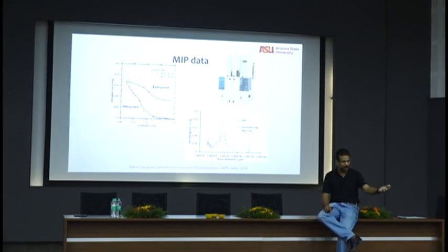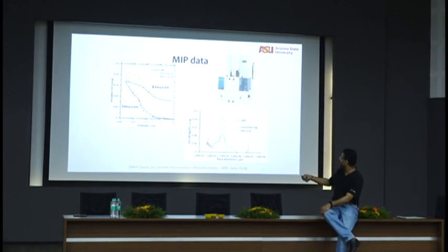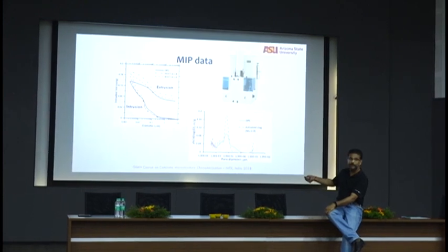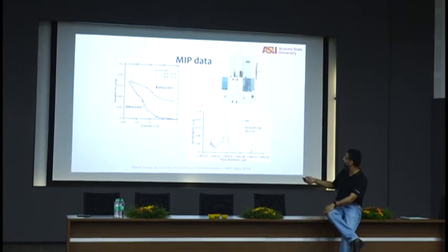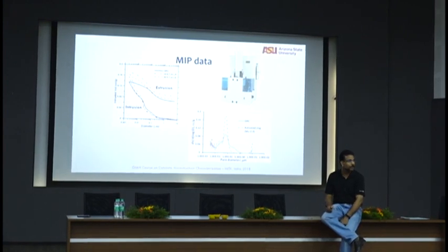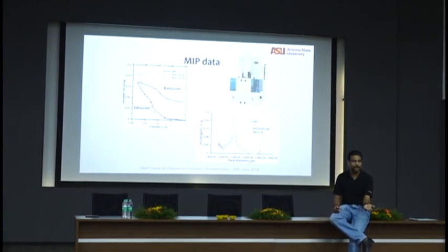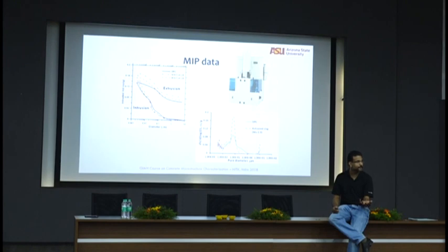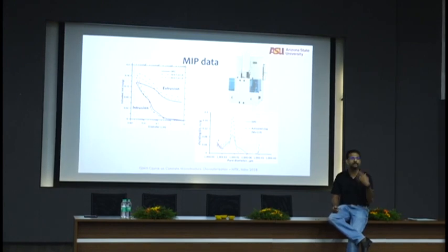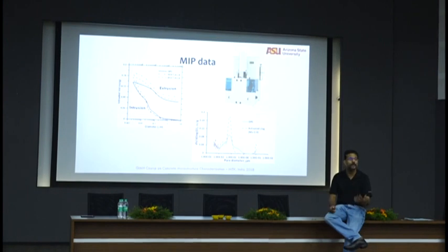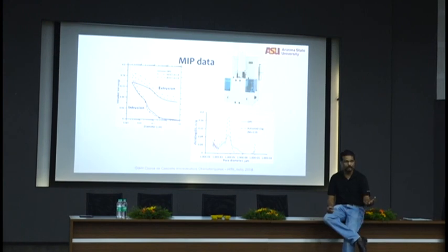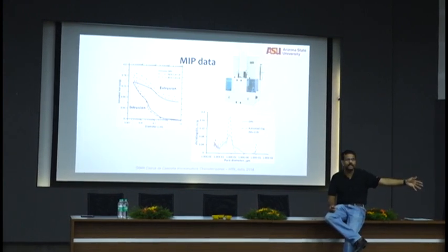That is one way. So if you take an OPC paste, take a fly ash paste, you will see the difference. And I've shown you here with some limestone, you see the difference between extruded and intruded volume, right? The more difference between extruded and intruded volume, the more complex the pore structure. More complex pore structure, good or bad? Good for strength, doesn't matter. So you want to create a more complex pore structure. Even though it's hard to measure, hard to quantify, you want in concrete a more complex pore structure. And the more complex pore structure can be engineered by using supplementary materials.